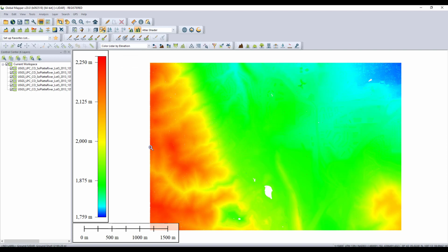Because Global Mapper preserves settings from prior sessions, if you've previously altered the symbology selections, your display may appear differently. If needed, use the drop-down menus to display the LAS tile with the settings seen here. When working with many large LAS tiles, it is sometimes helpful to clip point cloud data to a specific area of interest to save processing time and storage space.